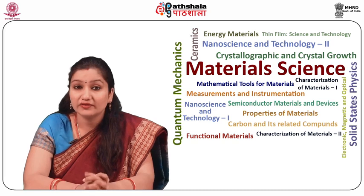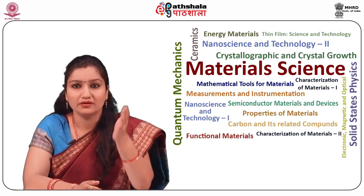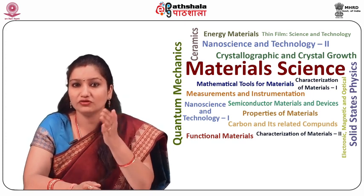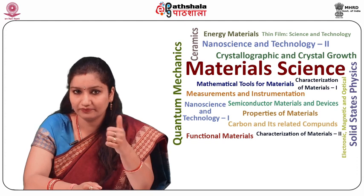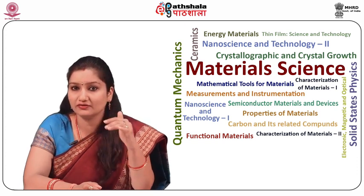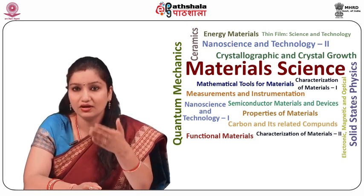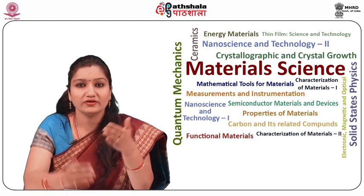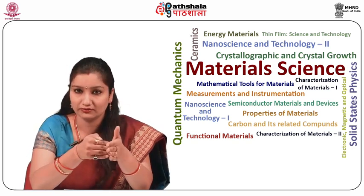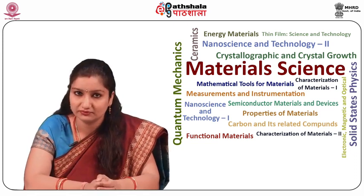Thirdly, failure occurs in a number of stages. For example, first of all, accumulation of defects in the material, first stage. Nucleation of fatigue cracks, second stage. Then the gradual propagation and joining of some cracks into a single main crack. And finally, the rapid final destruction.